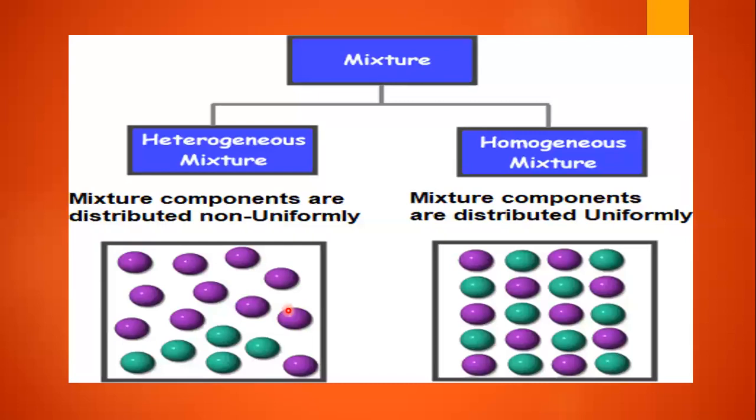If we have more pressure and temperature, the density becomes high, so there is less dispersion within the air. Otherwise, if the density is less, dispersion is going to be more. That means the fuel will travel throughout the air and touch the cylinder walls, which is not advantageous. This is because of improper mixing, so we need to advance this part.